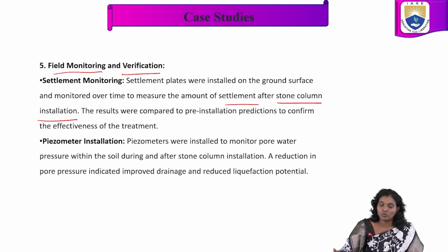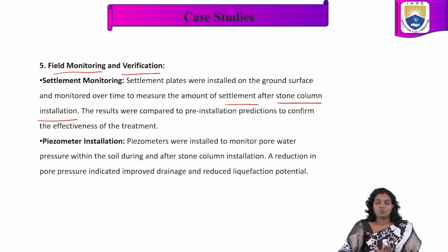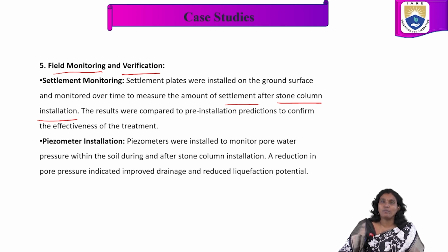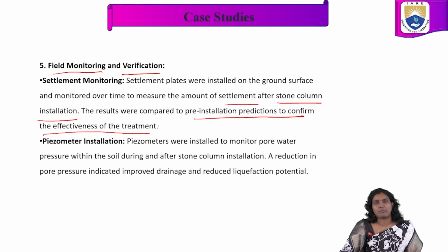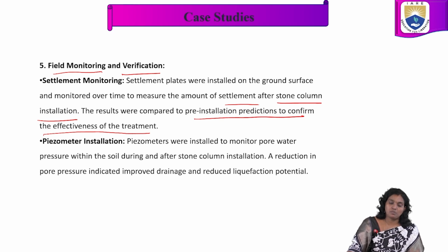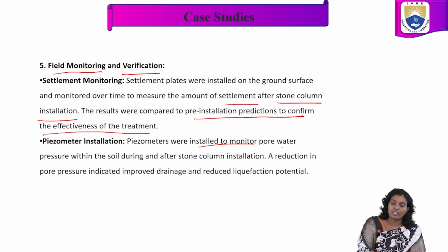We are going to understand the settlements of stone columns, and this settlement monitoring is very, very important. These results were compared to pre-installation predictions to confirm the effectiveness of the treatment. In piezometer installation, the piezometer was installed to monitor pore water pressure within the soil during and after stone column installation.